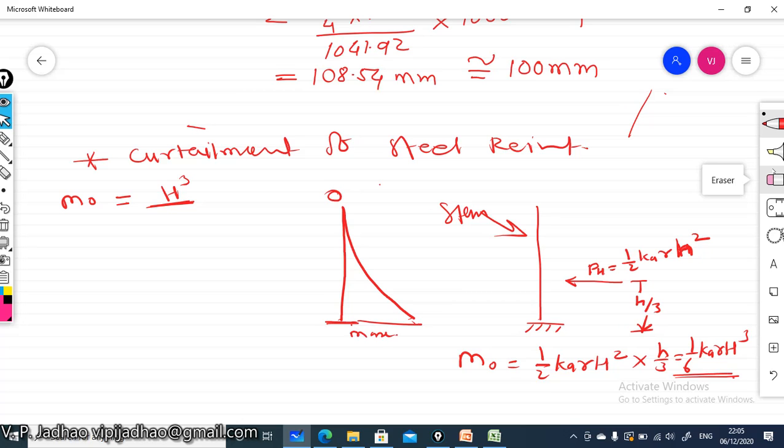Therefore, if we are providing some steel here for this maximum bending moment, at this particular location the bending moment will be, let us consider, Mx. This will be small as compared to Mmax. Okay, if we consider some location here, again this bending moment, let us consider My, it is again lower than Mx. Therefore, complete steel reinforcement throughout the length is not an economical option.